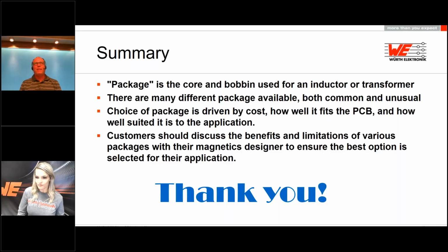A lot of it will depend on how many winding turns you need on your secondary side winding. Triple insulated wire is usually sold by the foot. So if you have a transformer that requires 5 turns, it might be better just to use triple insulated wire. If you have a transformer that's going to require 50 turns on your secondary side, that can get pretty expensive. And in those cases, margin tape will often be a more cost-effective option.